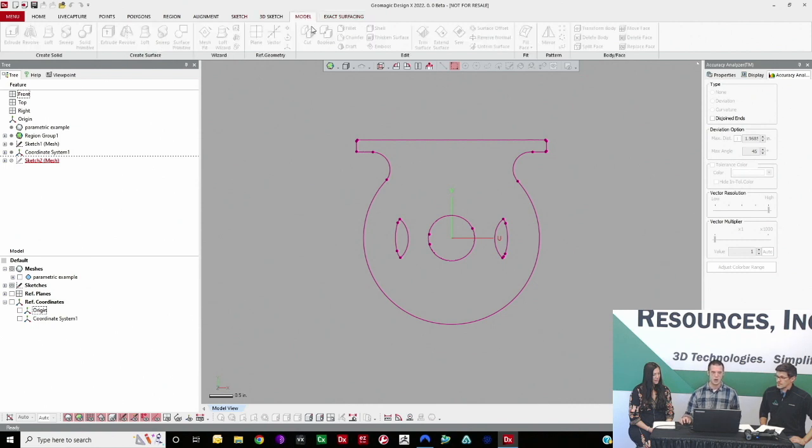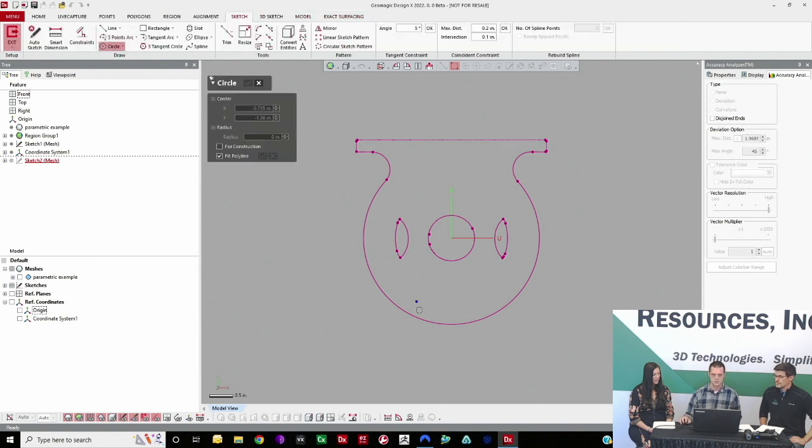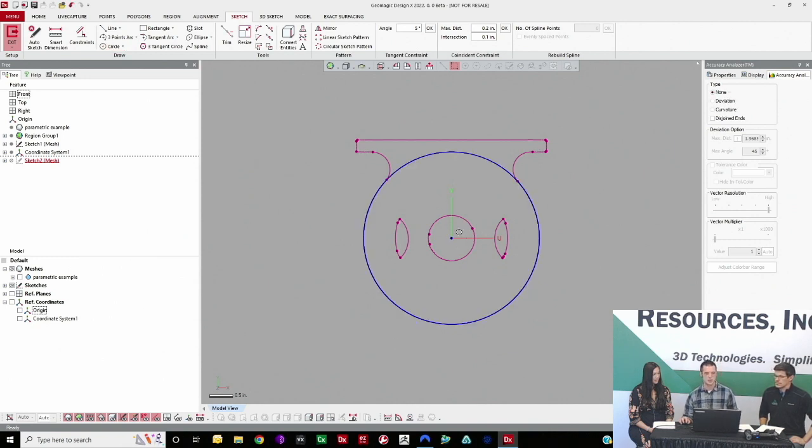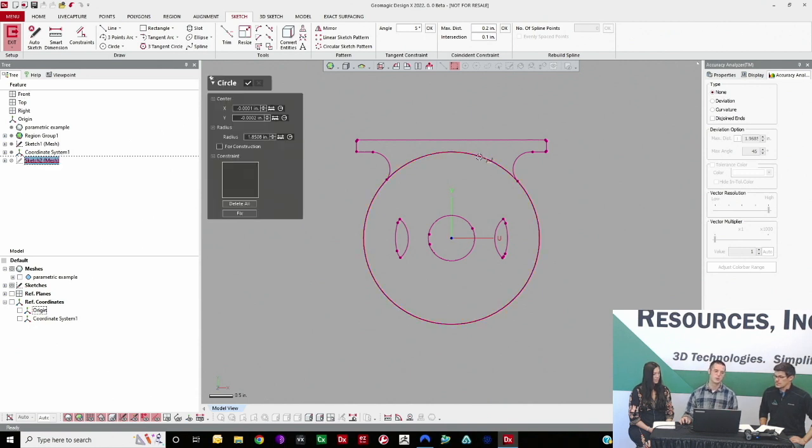Under my sketch tab, I'll go ahead and do another circle and just double click to best fit a circle. Now, remember, we put the origin at the center of the part here. So design intent would make it so that I should probably put this perfectly on center as well, since these two are probably supposed to be perfectly concentric to one another. And notice that I'm actually 1/10 and 2/10 off center, which is actually pretty good. I'm pretty impressed with how precise that is just on the part. But just to make that perfectly 0, 0, I'll make sure that's dead on center.